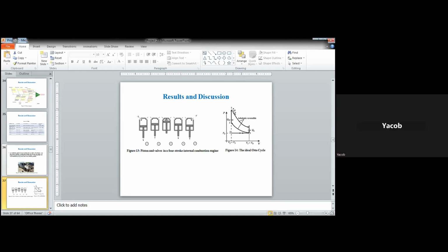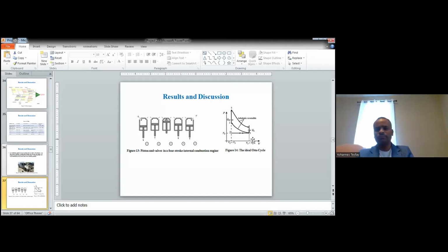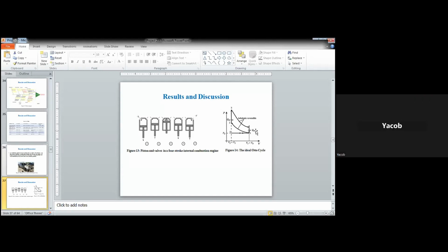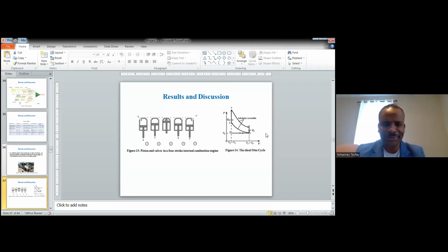Heat addition during compression, then spark at the end of the compression. So that is what it shows, 2 3, this QH. QL means rejection. Later, as it goes back down, the piston exhaust is the heat rejection. Then these two will be intake and the other stroke.